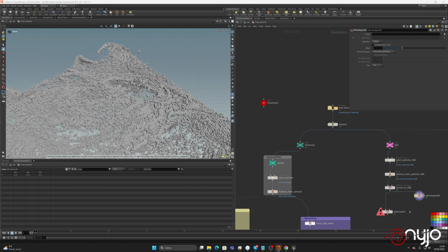Let's go back to manual, connect here, and in the VDB smooth we can try in this way and say out update. Now it takes a little bit to smooth everything, so we can, for example, lose some small particles, having something that is smoother, but the problem is that obviously we are losing quality because it's something like a lower quality fluid mesh.